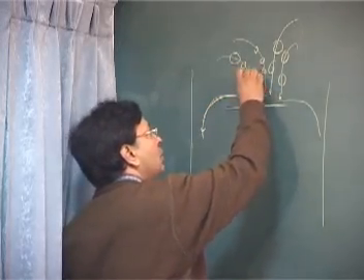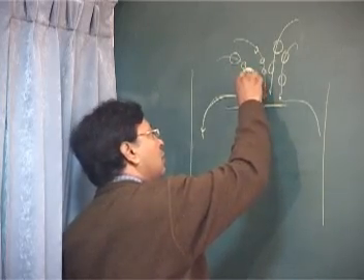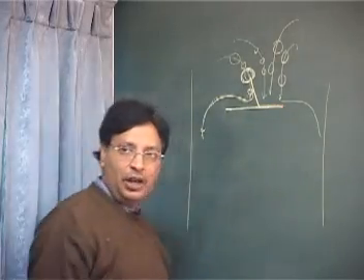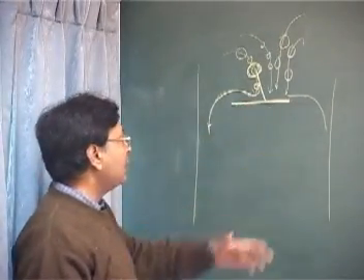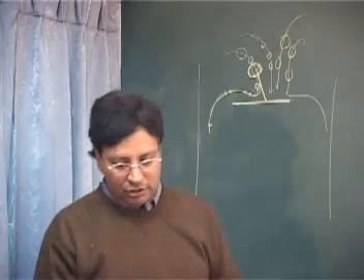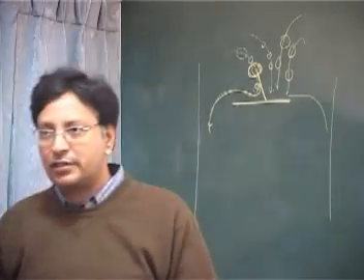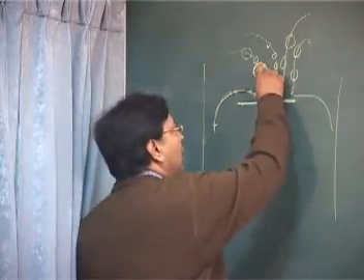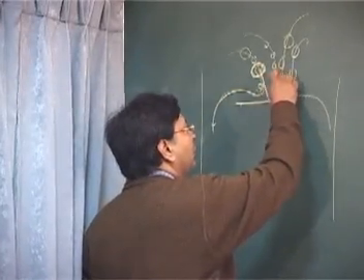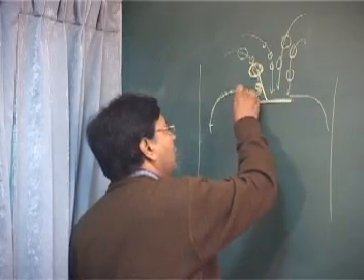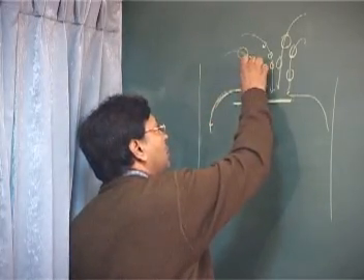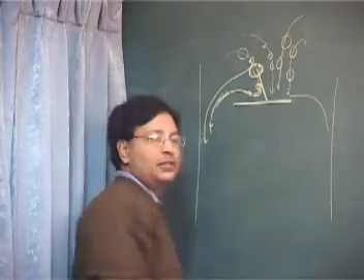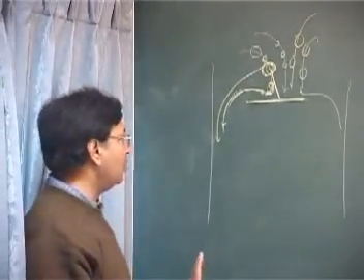So the larger particle which you see here goes and hits the plate. To capture this particle, if you wish, you can put a little oily surface, so once it hits it stays. The smaller particles, like this one, will continue to move out along the gas stream, and the larger particles will be stopped just based on inertia.